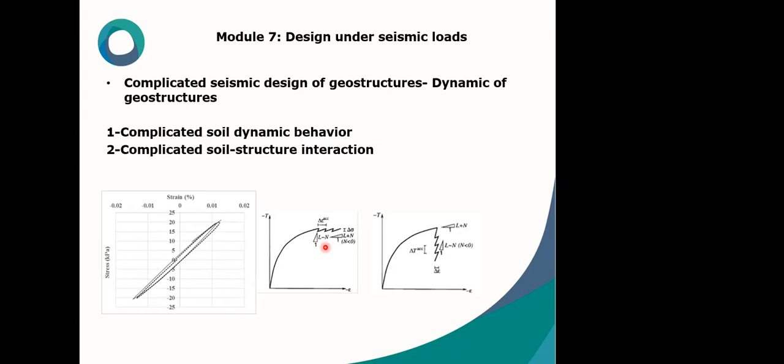The dynamic responses of above ground structures are evaluated by the inertial forces. On the other hand, underground structures' displacement does not differ significantly from the surrounding soil. Thus, their seismic responses are controlled by the ground strain and ground displacement, due to the soil structural interactions.